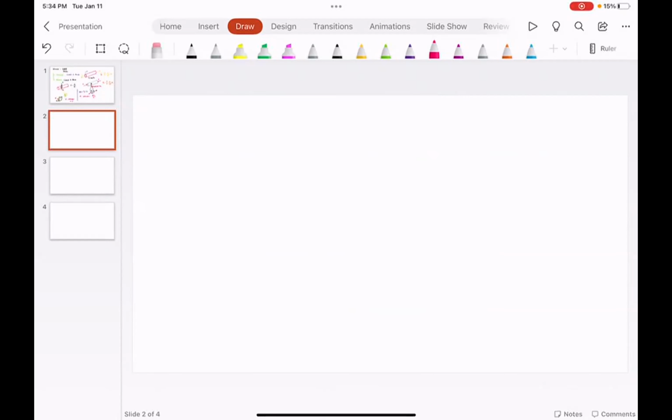So what is the takeaway here? Depending upon the material that you choose, you would use the appropriate theory. For example, if you are going to use steel, you would find the von Mises stress in your finite element analysis. If you are going to use some exotic material which shows the characteristics of the maximum shear stress theory, then you will find the maximum shear stress using your finite element analysis.